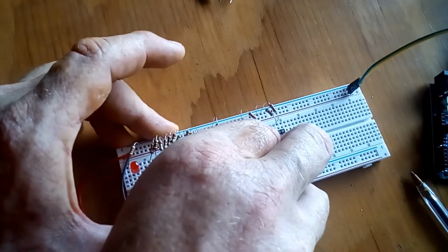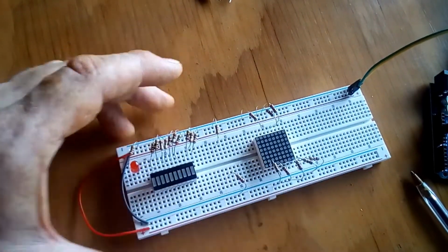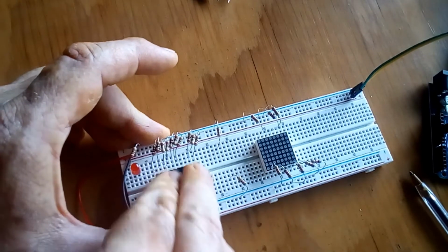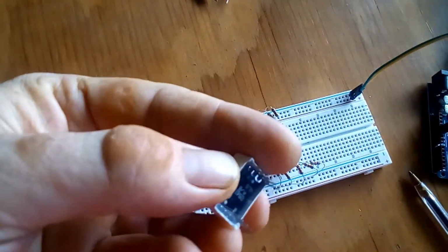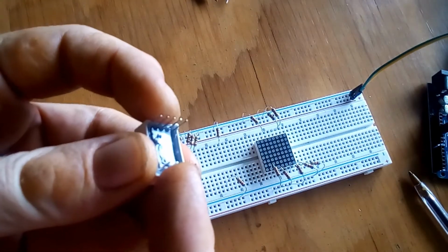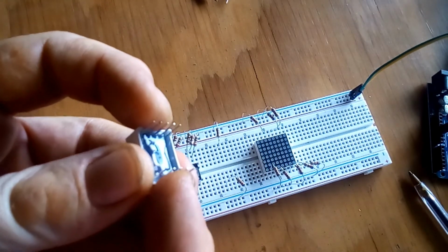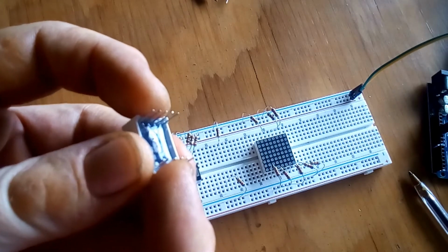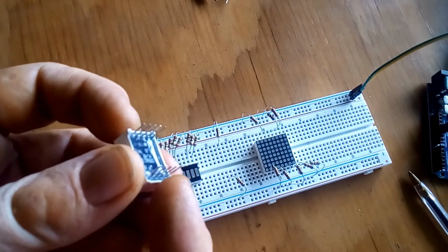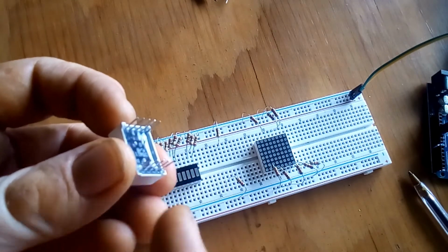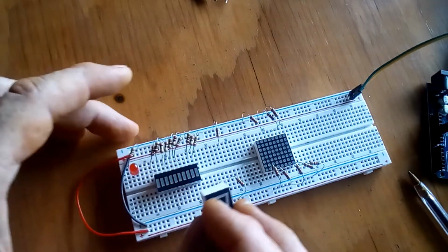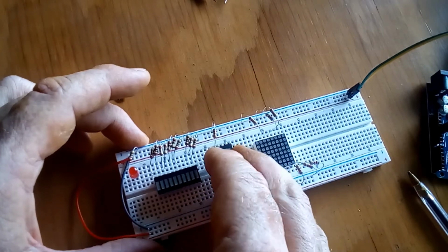Then the next one here, I plugged that in the wrong spot. Plugs up there. So on the back of the 7-segment LED, you'll see 10 pins. And again, this one had a common cathode, but it might have a common anode. So you just have to check. Put that middle pin to ground and then plug up one of the other ones and see if something comes on. If that doesn't work, put the middle pin to the positive rail, plug up one of the others to ground to see if it comes on. It'll come on one way or the other. So that's how we control those.